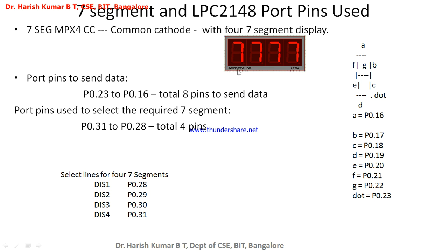So you can see here A, B, C, D, E, F, G, H. These are the anode terminals, and all the cathode terminals of this particular 7 segment display are connected together, and that is pin 1, the common cathode terminal of this display. Pin 2 corresponds to all the cathode terminals of the second 7 segment display connected together, and all the cathode terminals here are connected together, and it is pin 3, and this pin is 4.